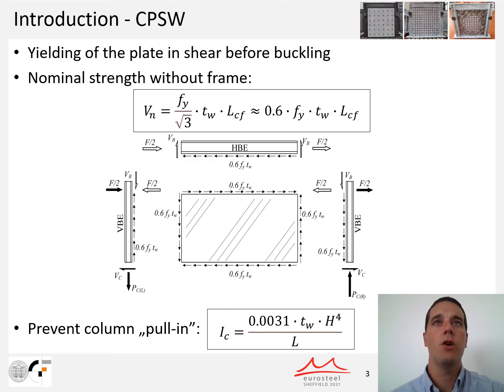In this case, nominal strength is at least 40% higher than that of steel plate shear walls and is calculated according to the following expression. The stress distribution in composite plate shear walls is shown on the figure below. The design procedure for these two lateral load-bearing systems is based on the capacity design approach, where the relevant member is either steel or composite infill plate panel.